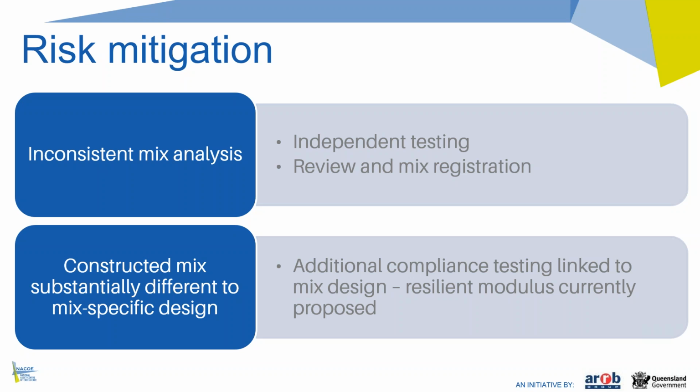The second major risk, which again relates to the use of the mix-specific modulus and fatigue aspects, is if the constructed mix significantly varies from the mix design. And again, that could lead to pavement performance being worse than expected.